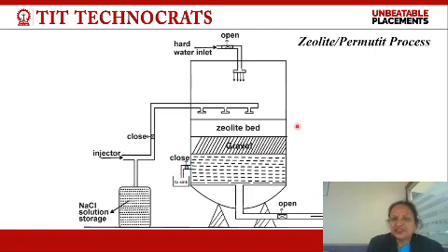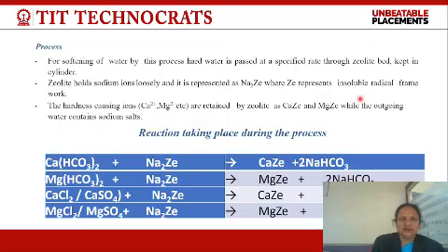In this apparatus, there is one zeolite bed. This zeolite bed contains many sodium ions, which can be easily replaced by calcium and magnesium present in hard water. This is the gravel filter, which will help us to filter the insoluble particles. Now we will discuss the process.